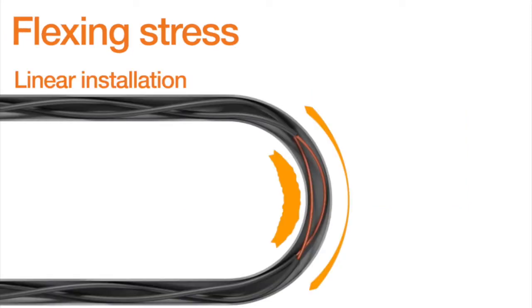Here we see a layered cable in motion, and you can see the length around the radius, the radius again being that curved part on the right hand side of the picture. And those two orange lines that we see show the different conductors and how they move inside of the cable. So one will actually have a shorter pitch, while the other on the outside radius of the cable will have the longer pitch length. And that presents an issue specifically for corkscrewing, because that means we have two conductors in the same cable that are essentially subject to a different amount of force. And that is one of the leading causes that can